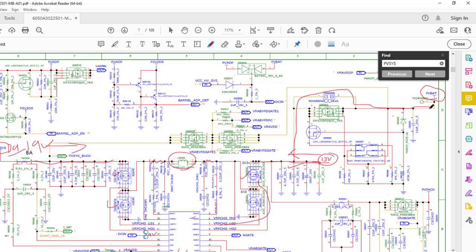So what you have to do is simply check this signal one after another, and this will output. And if the voltage is not coming, if the 13 volt is not coming over here, then you have to see why this voltage is not coming. So you have to go back and check the 19 volt here. And if the 19 volt is okay, then the previous sections are okay. And if the 19 volt is not coming here, then you have to go back and check the signal.